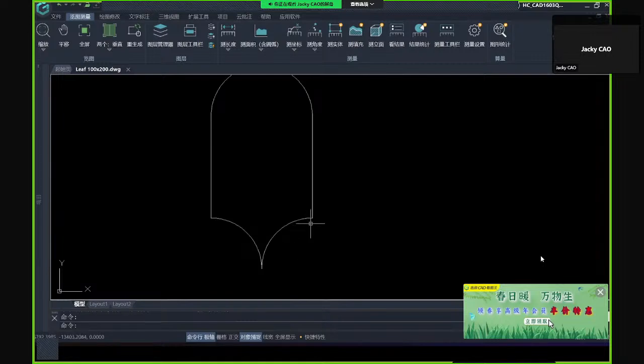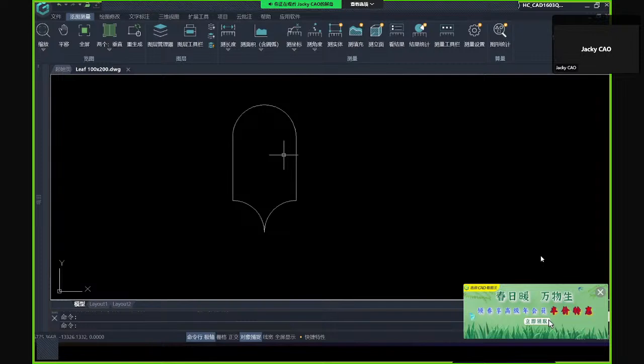And also pay attention to this: if you want all these elements to be continuous, duplicate those curved lines, this one to here, this one to here. Then you can have continuous section faces. Otherwise, if it is not continuous, we will have a very big gap. Try to limit the gap, it will help you. So just pay attention to that.